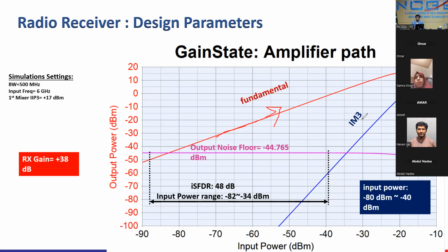So you see this point, the purple color line, this is actually the noise floor of the system. You cannot see below that noise floor. So at this point, you can see the signal comes out. You are increasing the power, and from minus 90, at this point it's minus 80, then minus 70. Around minus 80, the signal comes out of the noise floor. You are increasing the power, the signal comes out of the noise floor, and it is increasing.